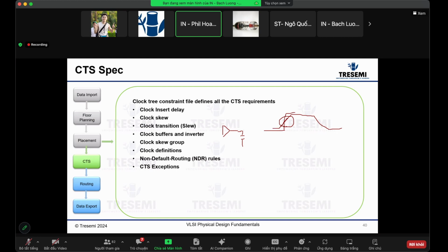And also be very aggressive for signal integrity or crosstalk. But you don't want it to be too slow either. So it is trial and error. If you have slow rise and fall, your skew might be worse.